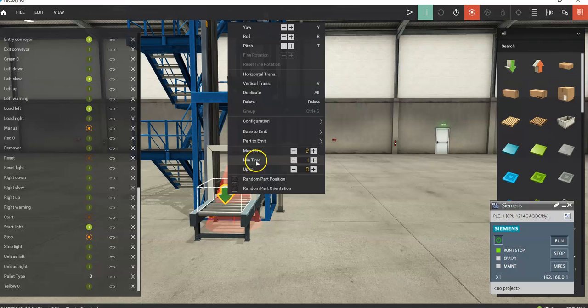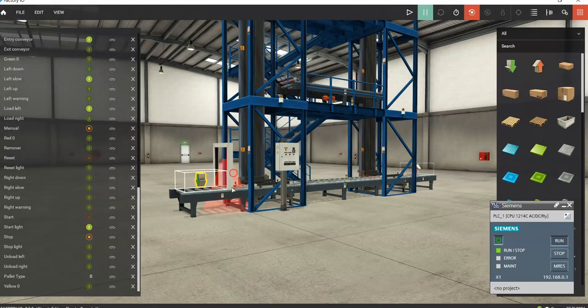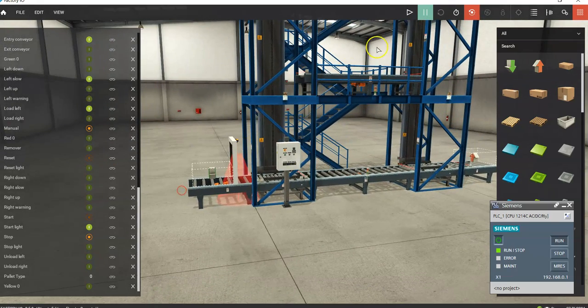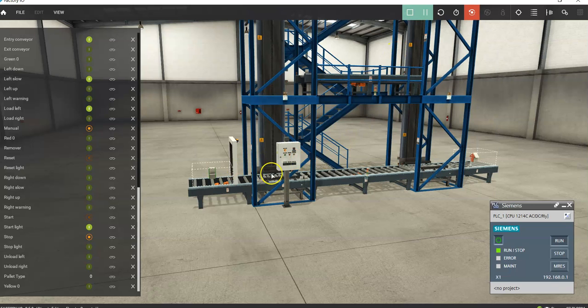And you can see here the parts, when the emitter's on, so you could also turn it on constantly, which is probably not a good idea, but that is the default condition. It would be putting out parts between 1 second and 2 seconds. And that would be a very hard task, because there's not enough time. Well, you could stop it right here, and the way it works is if you keep dropping emitter parts, while you're bringing one up, you can have it stop right here waiting for the elevator to go up and then come back down, and then you could load it. That makes it a little more complicated.